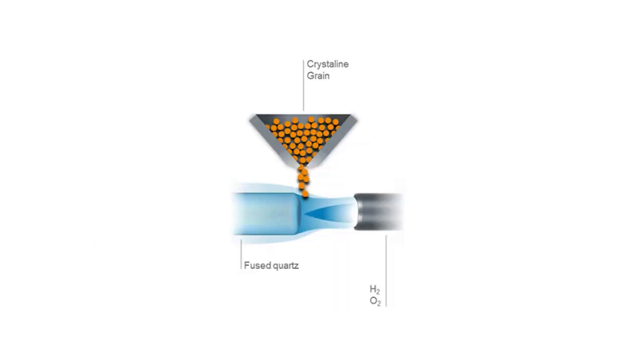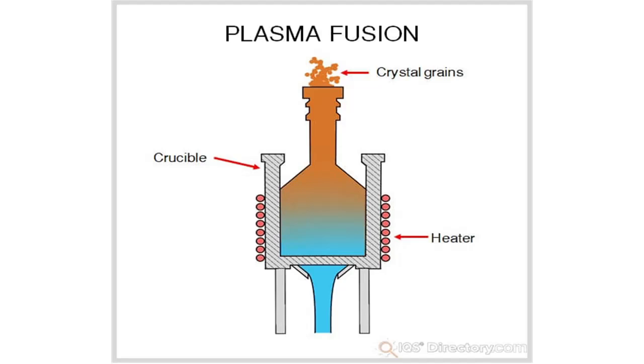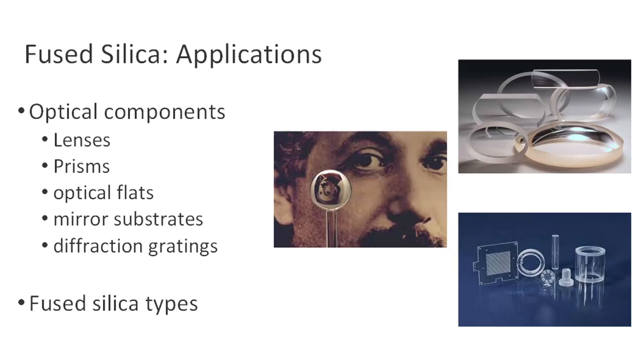Fused silica can also be made from nearly any silicon-rich chemical precursor, typically using a continuous process that involves flame oxidation of volatile silicon compounds such as SiCl4 to form silicon dioxide. The resulting dust is then thermally fused to form the transparent glass. This process results in a material with ultra-high purity and improved optical transmission, specifically in the deep ultraviolet, UV, range.